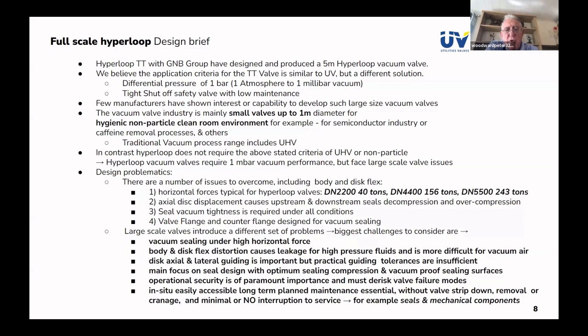It's quite normal with gate valves and knife gate valves to only seal on the downstream face with the additional sealing force. But we've developed valves previously where we've met this challenge of wedge displacement horizontally, and we've tasked ourselves with maintaining the inlet seal or the upstream seal tightness as well. And that's what we set out to achieve here, and we have.